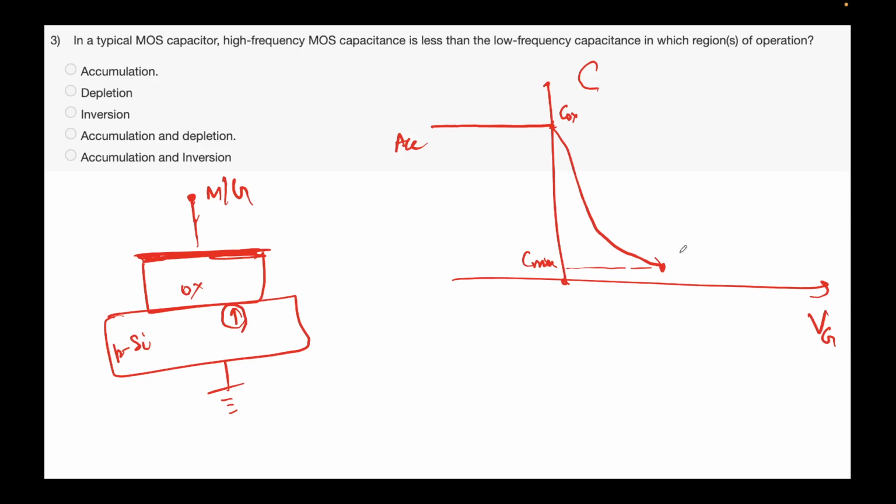The only thing is, this analysis was based on the physics of the band bending, why two terms come here, and the depletion happening. This phi ms is just the extra offset term, that's how I tend to imagine it. Okay, so this is the first non-ideality in a MOSCAP.